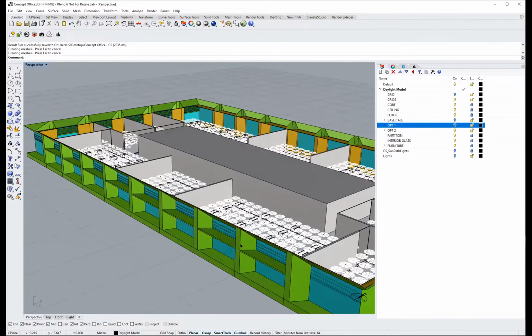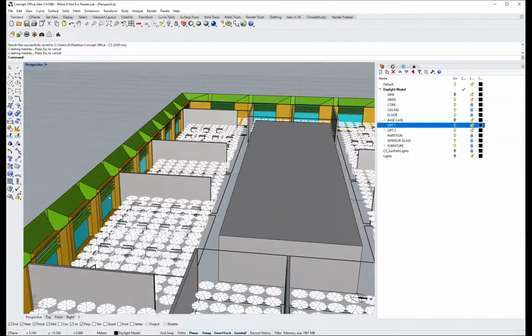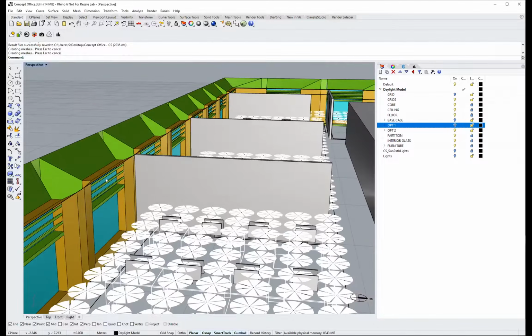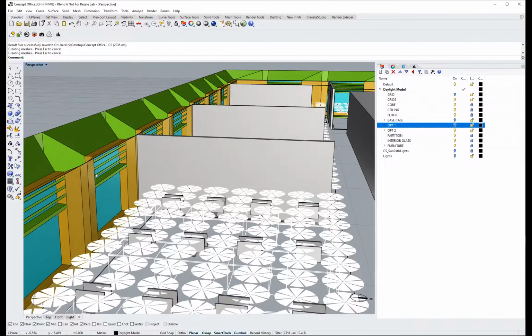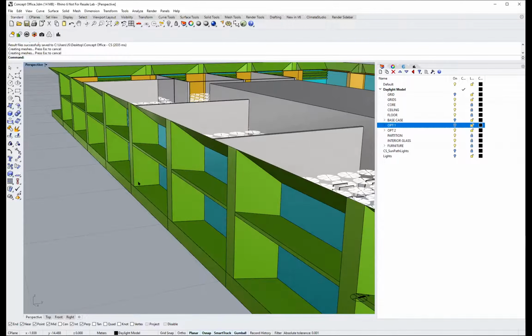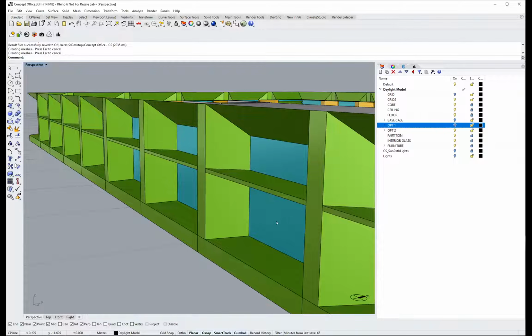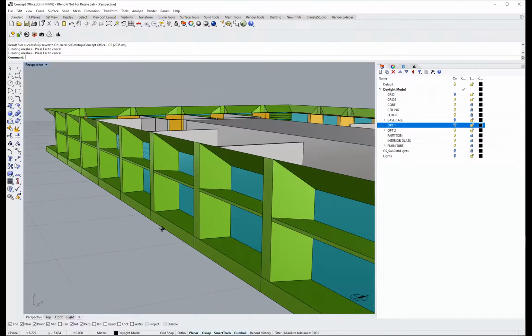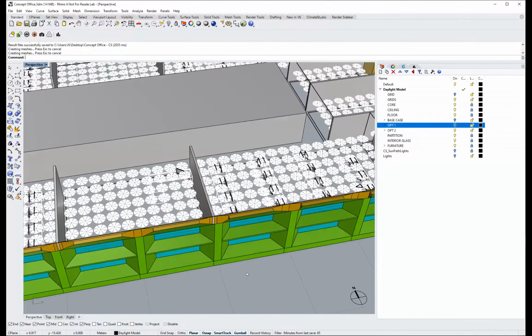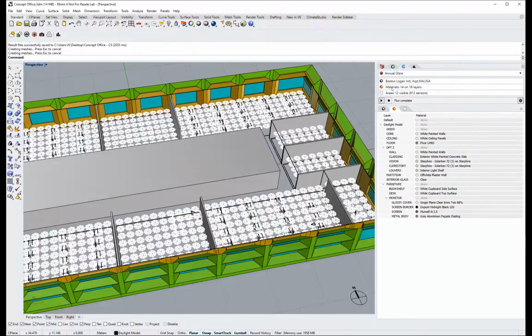Although now what I've done on the interior is add static louvers in the upper portion, the clerestory portion of the glazing, and then a light shelf which sticks out into the exterior that separates the vision glazing at the bottom from the clerestory glazing at the top. This light shelf could be interior for lighting purposes, but for energy, I'm just going to guess that this might provide some shading benefit in the summer. So with that switch, I can then restart the glare simulation and see if that addresses some of the concerns I have about my option 1.